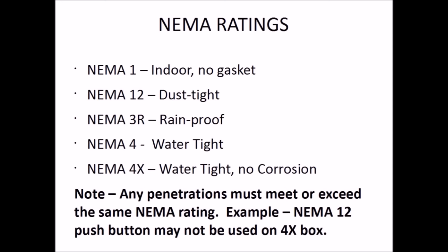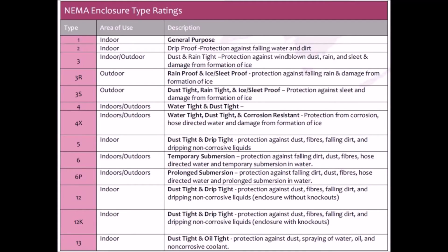In this chart we have NEMA 1 as general purpose, NEMA 12 dust tight, NEMA 3R is rainproof, NEMA 4 is watertight, and NEMA 4X is watertight, corrosion resistant. This chart lists what I just mentioned and a few others like NEMA 6 and 6P.